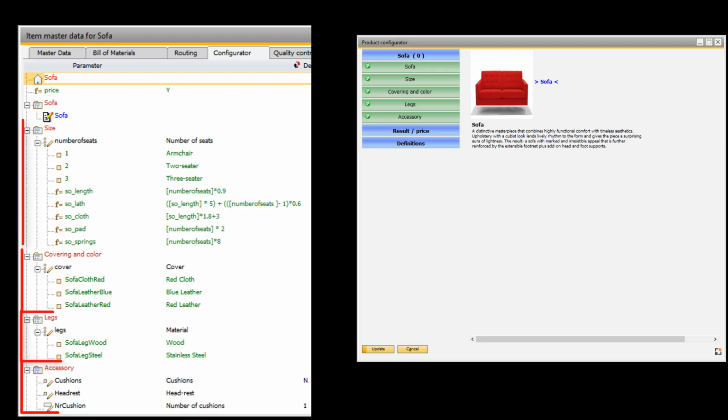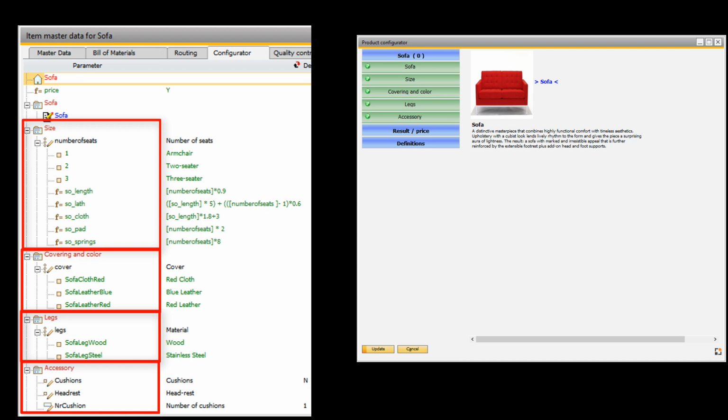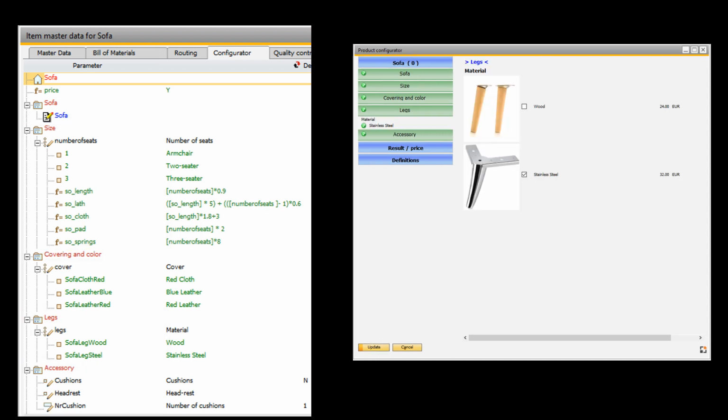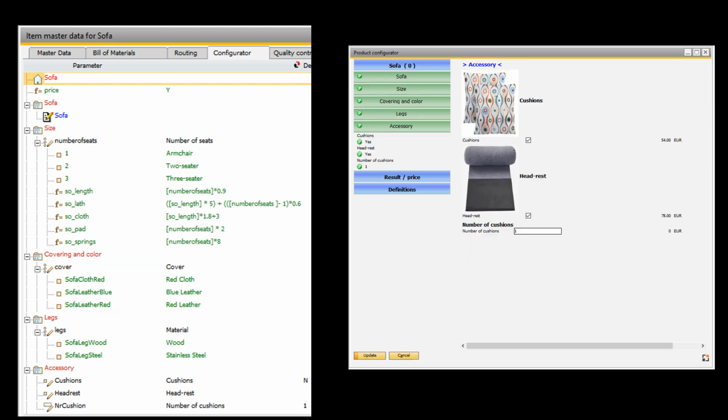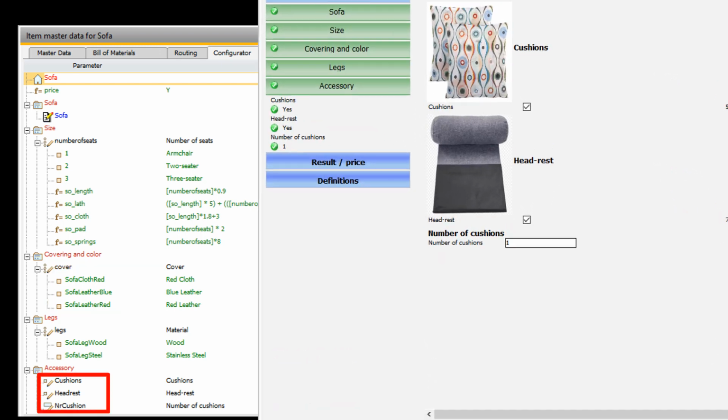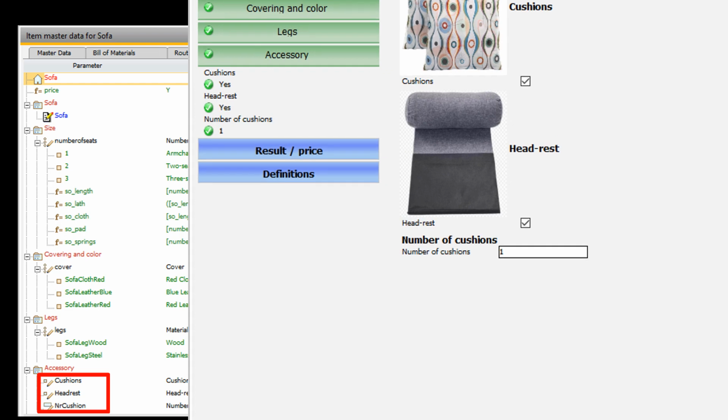A block configuration can be used for grouping certain elements. Blocks are represented by different icons in the configuration structure. The set object is a variable to which you can assign a value or formula. A parameter is used for input or selection of possible options in the configuration, normally with alphanumeric values, checkbox, or selection. A selection always refers to a superordinate parameter. The selection object is displayed as a radio box or a drop-down list only in case of an assigned reference.